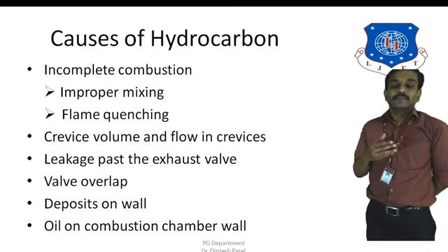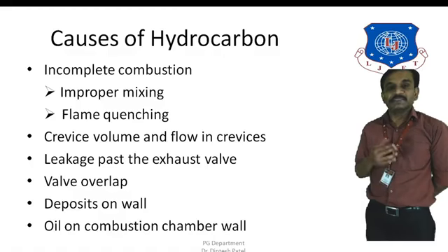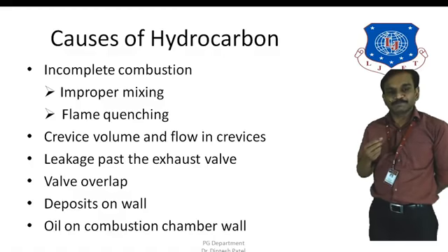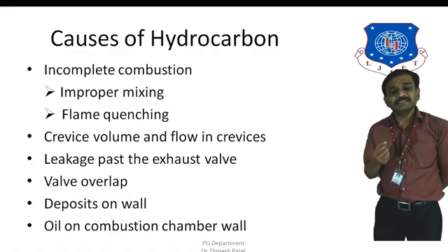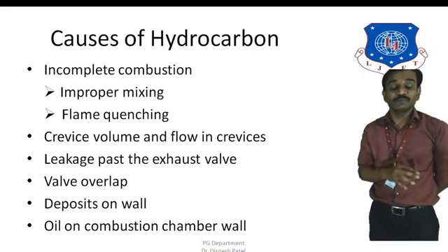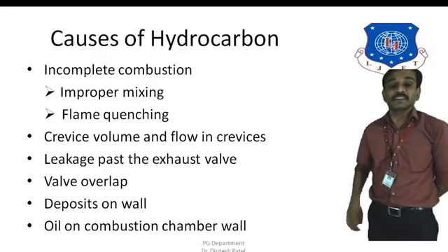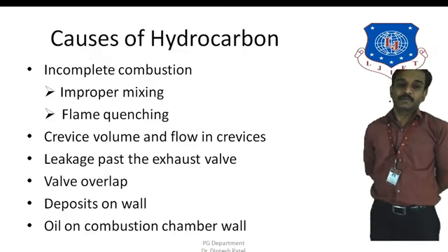And one more reason for that is, as the vehicle gets old, the engine is old, these rings would get eroded, their size would reduce, and therefore the crevice volume will increase, and much more fluid will enter into the crevice. So we need to look into these piston rings to reduce the hydrocarbon.